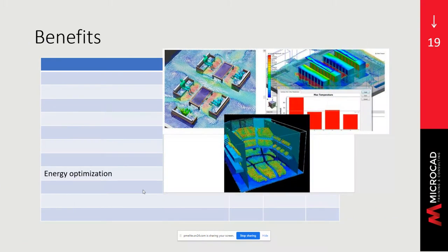Energy optimization. More and more owners are concerned about energy use, both because of the cost and social awareness. Green buildings can be built, but they have to be operated in a way to maintain that greenness. Automated HVAC systems, moving shades, air control systems, all are ways of operating the building at maximum efficiency. The digital twin could be used to analyze energy use and model the control systems. It can then be used as a basis for the testing of alternatives.